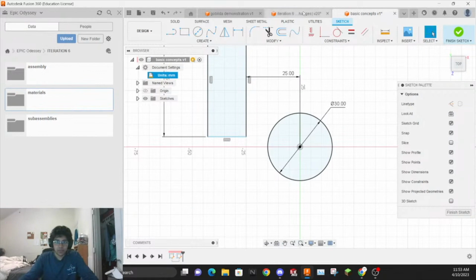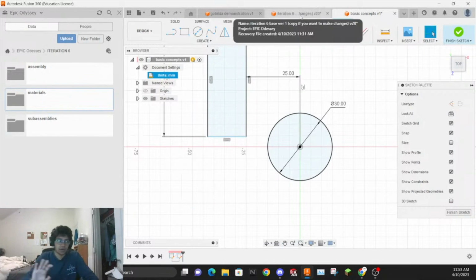That was extremely important with our custom parts, because we had to say, okay, now we're in our robot and we want to make this custom part that holds up our idler bearing. Well, how do I do that? I'm just going to dimension a sketch from the certain plane that I want, and I'm going to dimension it so it's this distance away, this distance up, this distance down, correct? And that lets me orient everything in space.